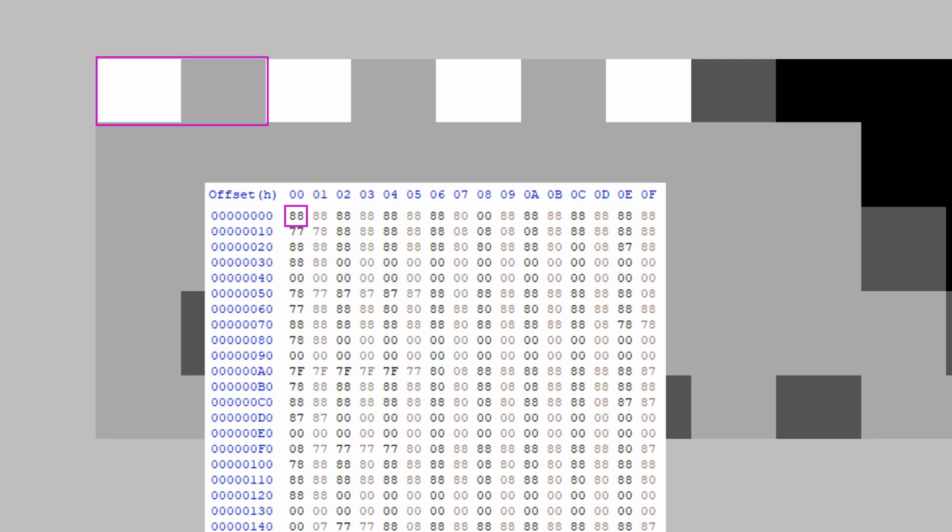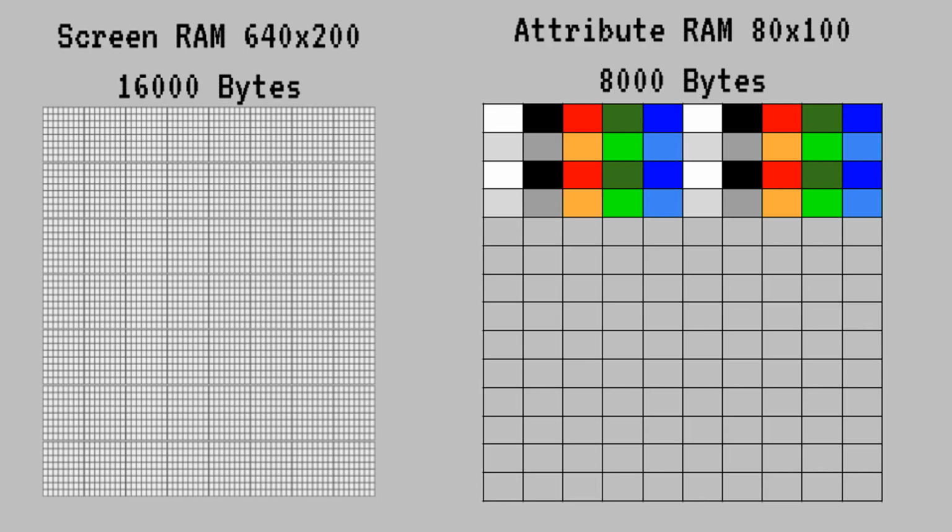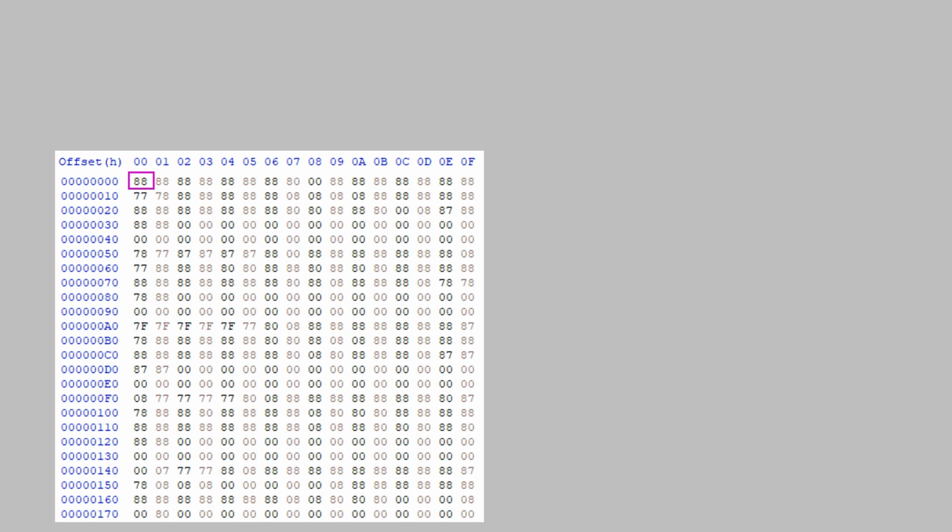Now we come to converting the image data. The CGA-Lowres data file is set to contain 2 pixels per byte. The high nibble contains the left pixel, the low nibble contains the right pixel. As mentioned earlier, this is not how the VDC lays out data in memory. We'll need to write color information into the attribute RAM and information about pixels showing background or foreground colors into screen RAM. First step is to separate high and low nibbles.